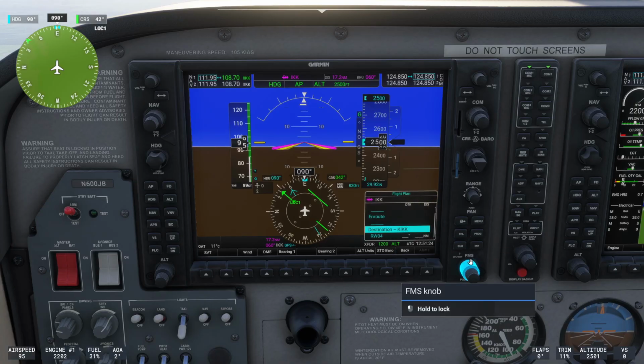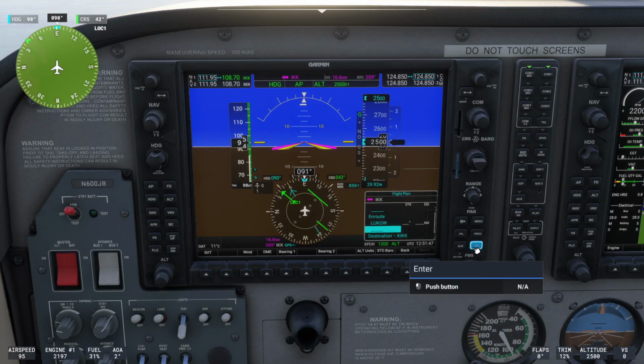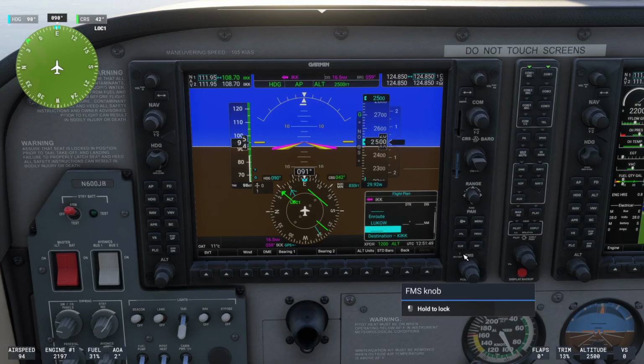Next, if we go to the flight plan and go to the en route section right here, what I like to do is use this en route thing as kind of a standby GPS. So loading up any waypoints we need to use later in the approach, just preemptively. In that case, we're going to be using our locator outer marker as a GPS waypoint as well after we're done with the DME. So go ahead and load that into the en route flight plan section.